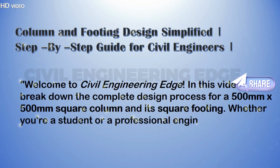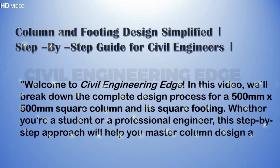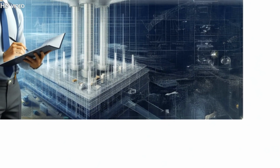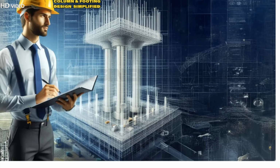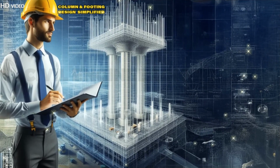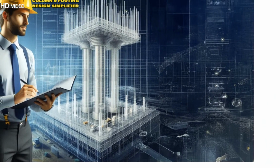Section 1. Given data and problem statement. We have a 500 millimeter by 500 millimeter square column carrying an axial load of 1,500 kilonewton. The safe bearing capacity of the soil is 225 kilonewton per square meter, and we are using M20 grade concrete and Fe 415 grade steel. Let's begin by designing the column reinforcement.